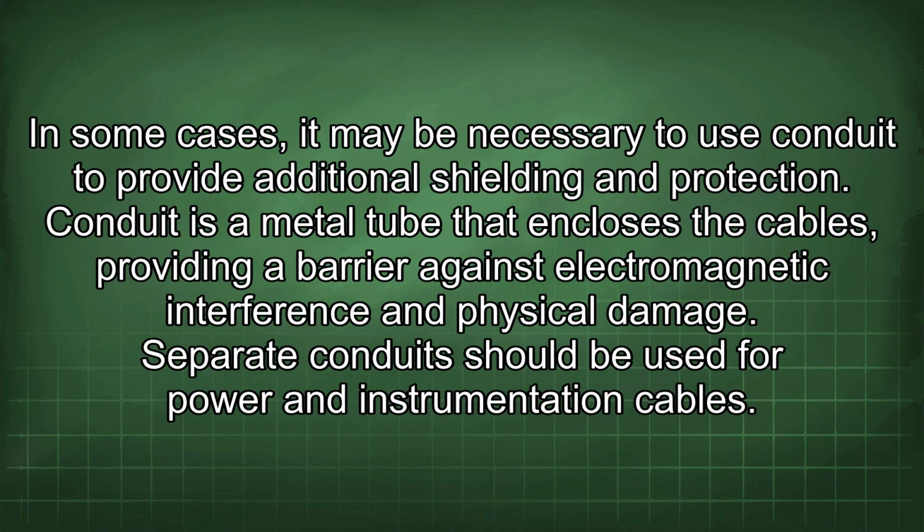In some cases, it may be necessary to use conduit to provide additional shielding and protection. Conduit is a metal tube that encloses the cables, providing a barrier against electromagnetic interference and physical damage. Separate conduit should be used for power and instrumentation cables.